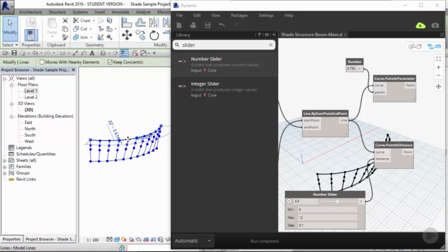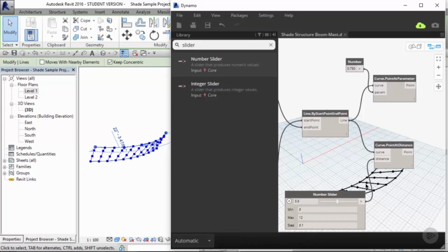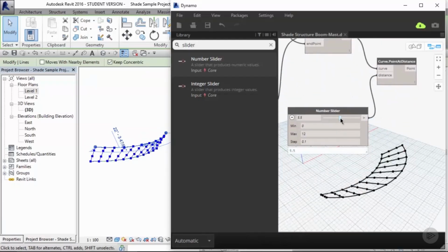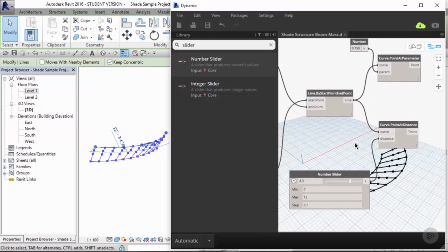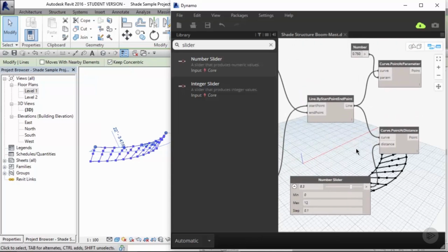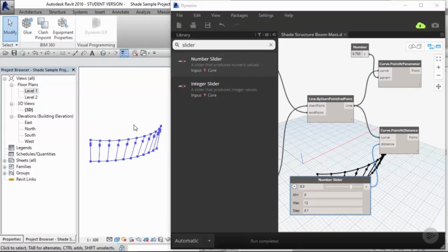In Revit, if I modify the location of one of my model curves and lean the entire assembly forward a little bit, you'll see that the lines now remap to the new location of the model curve above, and my parametrical relationship, my point along that line, still maps properly to some parameter directly along the line, even though the length of these lines has now increased.